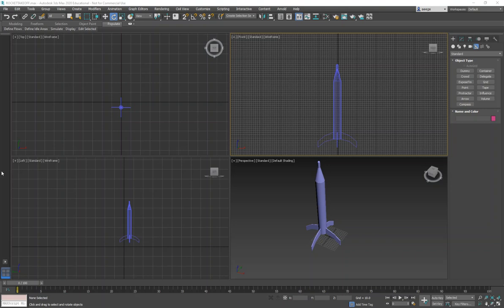To do that, I'm going to go to the Create tab on the right-hand command menu. The Create tab gives you helpers, 1, 2, 3, 4, 5. The 5th icon from the top right is a triangle-shaped helper, so click on it. There is a Tape option. When you click on the Tape option, it gives you the length of the tape. We're talking about 36,000, so I'm typing 36,000.